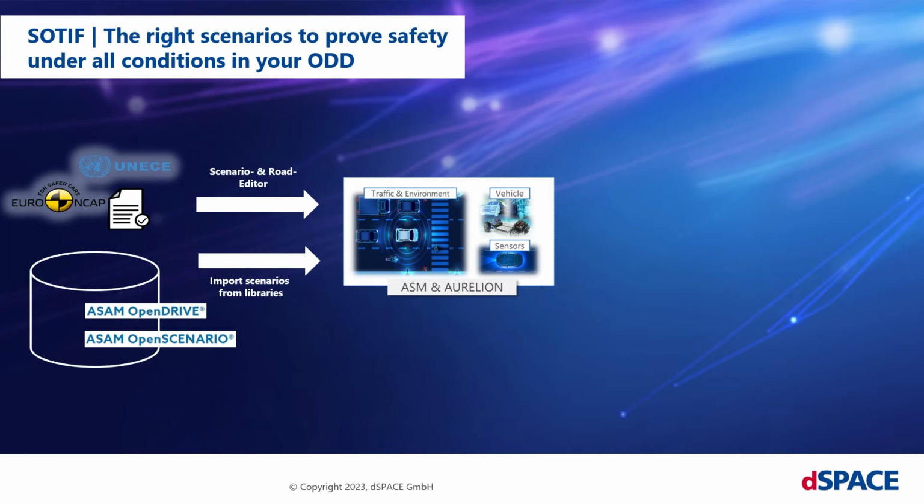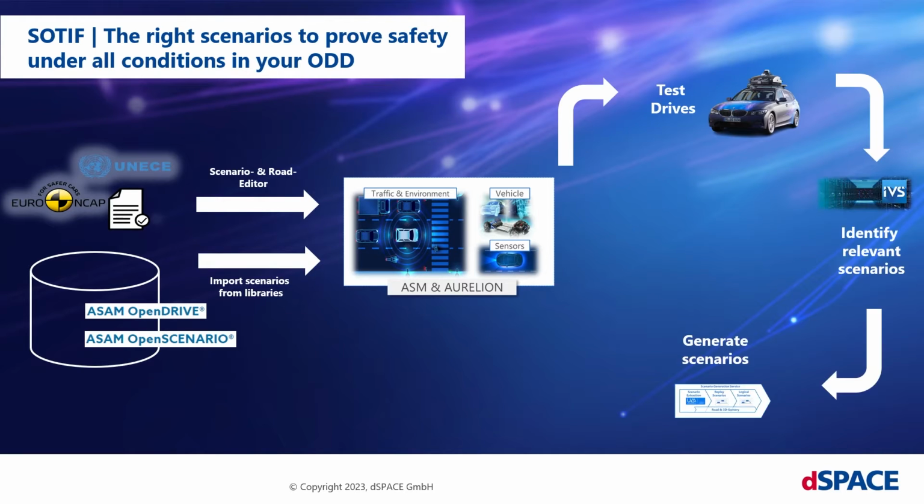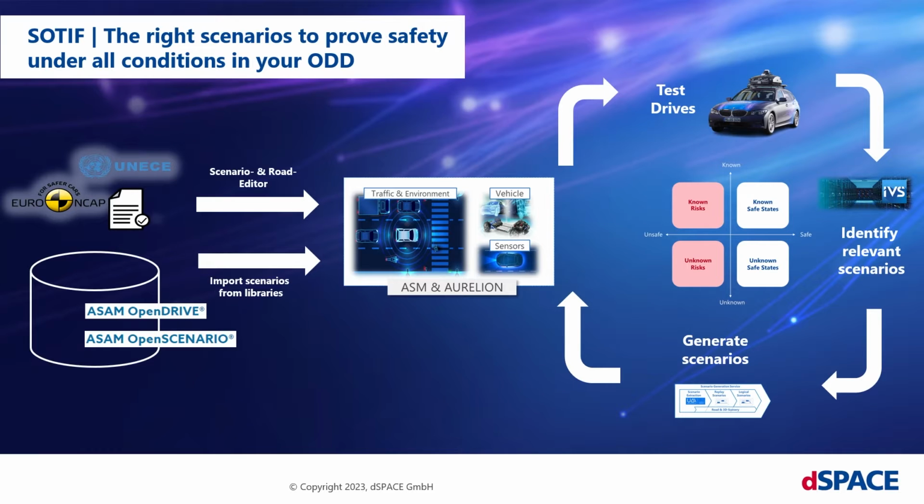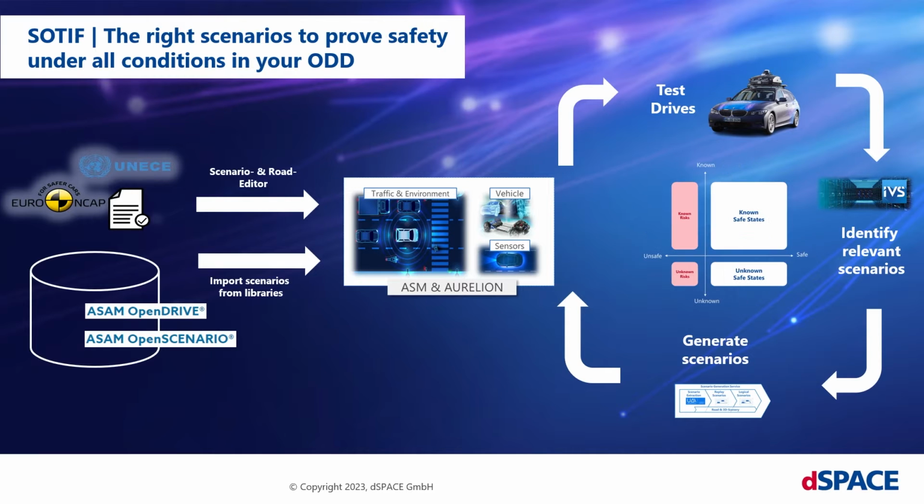One possible approach is to increase the number of simulation scenarios in your test campaign by importing scenarios available in public databases, making use of the standards OpenSCENARIO and OpenDRIVE. Finally, you should also make use of experiences and knowledge you gained from test drives in the real world. By analyzing the data recorded in your test drives and virtualizing the experienced scenarios, you can extend your scenario databases and additionally increase trust in your virtual testing as you include relevant scenarios that occur in the real world when driving with a tested function, including all the complexity and realism of the real world.